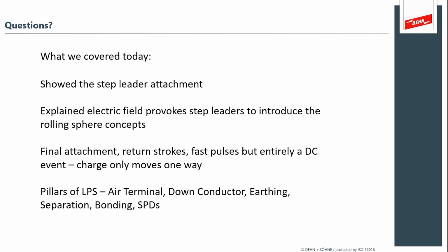So when you go into the intermediate, can I do a 2.5? Well, you need to design the material to also withstand what the IEC standard will dictate. So there may be methods to become, let's say, more risk controlled, but you still need to look at the standard for what the high end might also be. Because remember, it's a high and a low end of the strike.